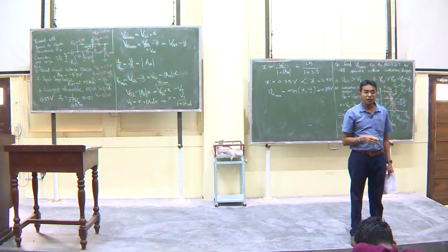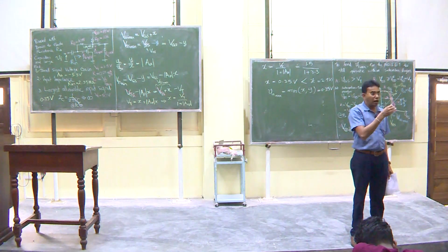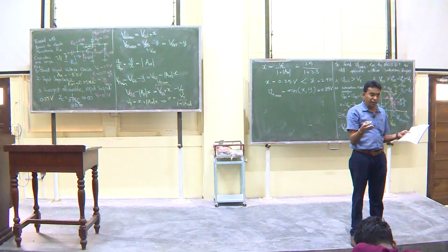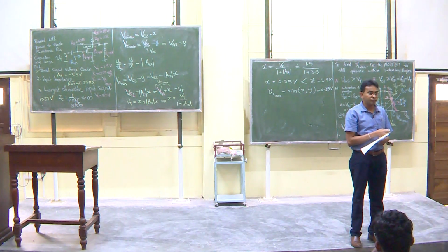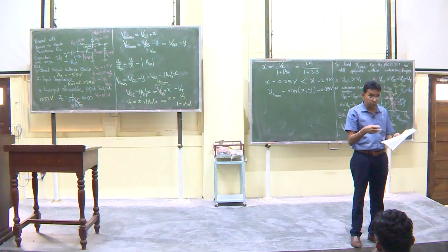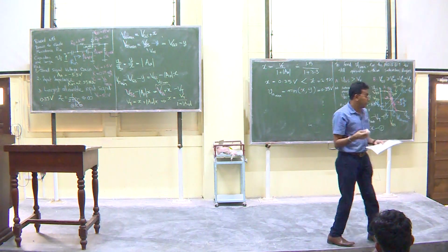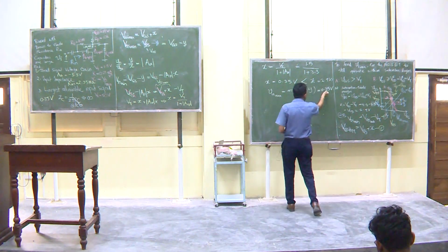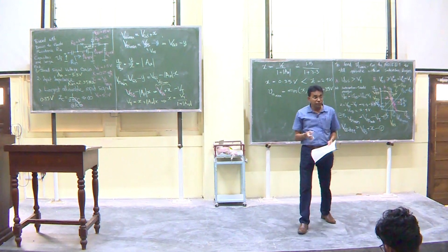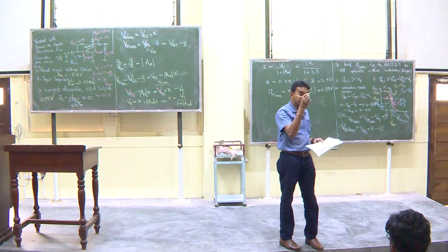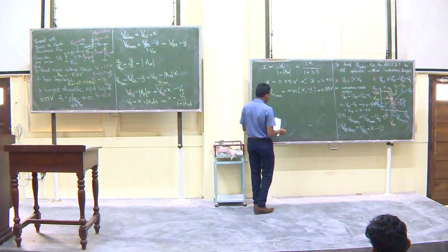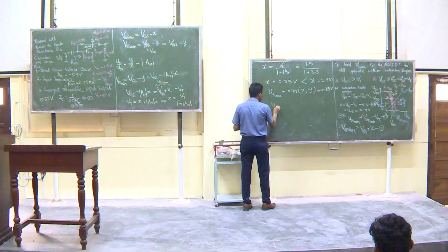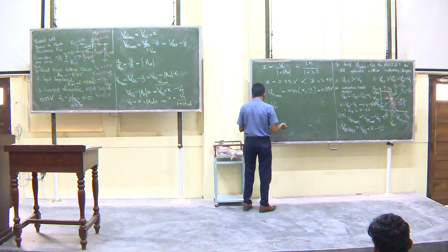In that case, our calculations are correct, but the amplifier may not work as a linear amplifier. The non-linearity effects are much bigger then. But with 0.35, since 0.35 is much smaller than the DC overdrive voltage.